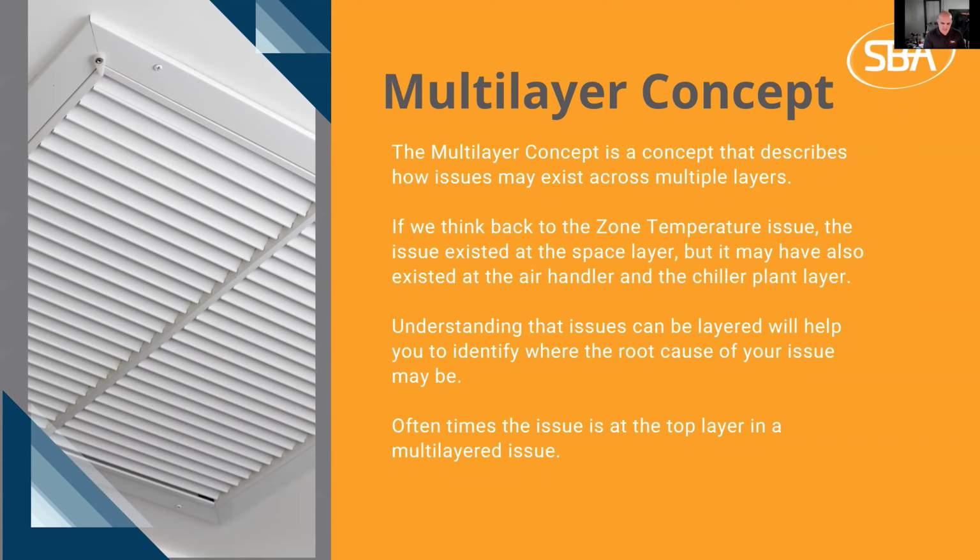It's so easy to focus right on the zone temp, because us being in a calm situation right now, we're like, okay, yeah, we would logically just say, oh, well, what else could be going on? But when you're trying to get something solved really quickly, you can have tunnel vision. And you've got to fight that temptation to tunnel in and step out and be like, okay, what are the space conditions? What are the air handler conditions? What is the hydronic? And always be asking yourself, what could cause this, and work your way up. That is the multi-layer concept.